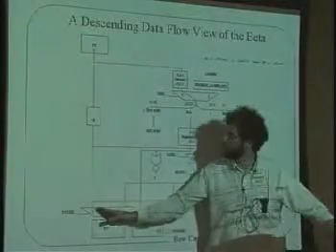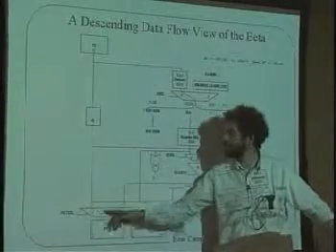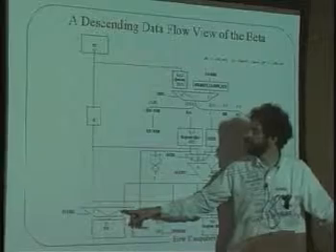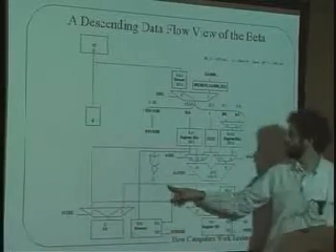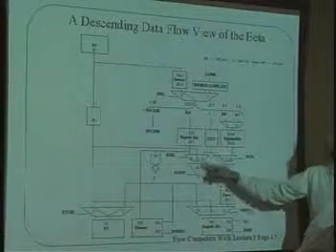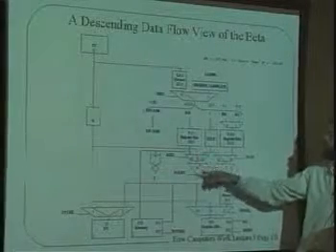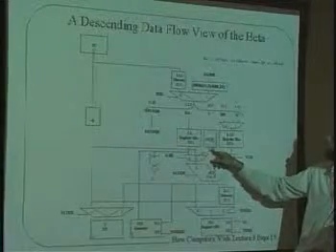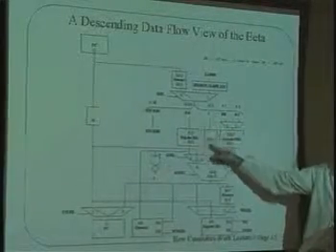If, on the other hand, PCSEL is set this way, and that's why both of these are red here, if we choose this path, then the PC will be loaded with whatever pops out of the ALU. And what's going to pop out of the ALU is going to be PC plus 1 plus, and we're going to set this to plus, what comes out of this path, which is the sign extended constant C.